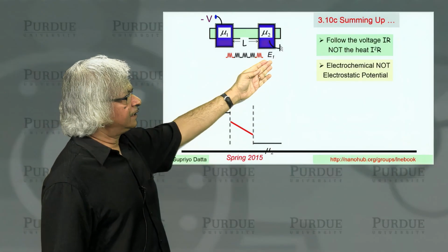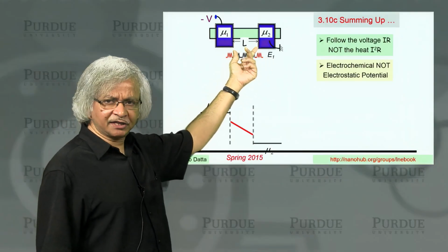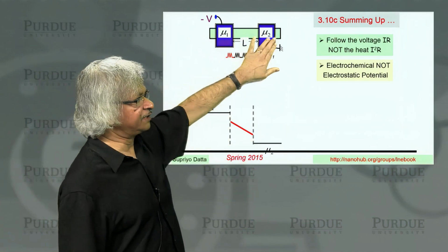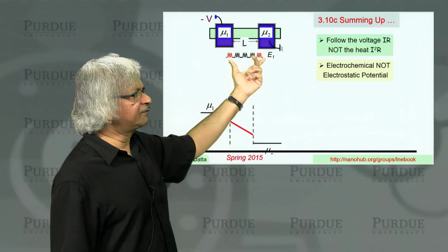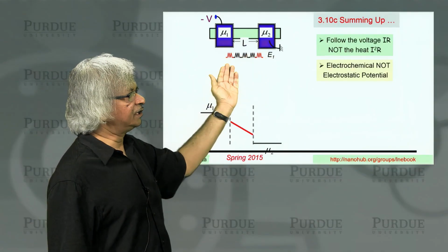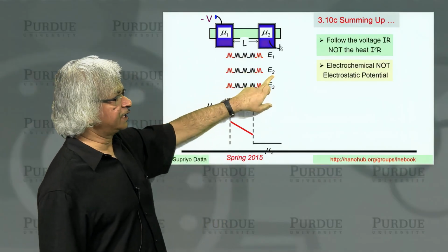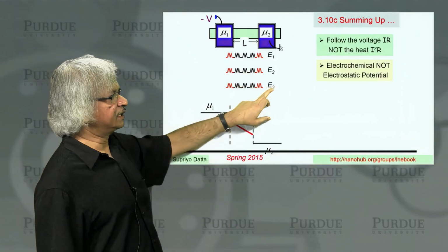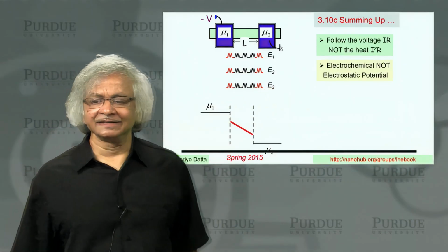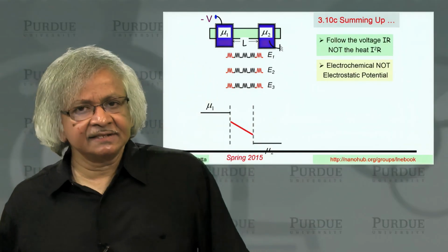that the general approach we have been using is that we talk of a small section in which we can ignore the inelastic scattering. So all the inelastic scattering is in the contacts. And so different energy channels are all independent. So for a particular energy, you could think of it as a series of resistors. If you look at another energy, you got another set of resistors, another energy, another set, and so on. And what you have ignored usually is the inelastic scattering in our thinking.